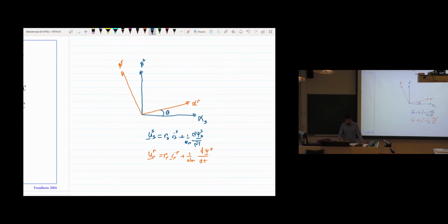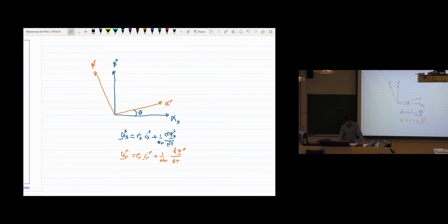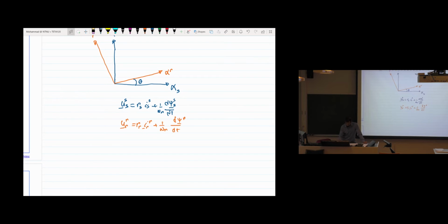And then next step, what we did, we converted the rotor-oriented frame into a stator-oriented frame. So if we convert them into stator-oriented variables, then what we did, we changed this d theta into d dt minus j n, and this n is d theta over dt. That gives us the n here, the speed of the rotor.